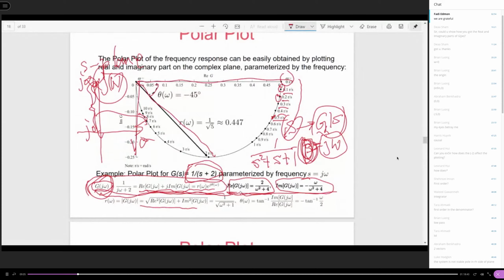You can use this one, then you only deal with the real function. This is our own real function. But you can also deal with the complex function, which is here, and that complex function maps j omega to this semicircle. So that introduces another way to draw a more complicated polar plot. Why? Because we have not considered the lower part, which represents minus j infinity to j0.